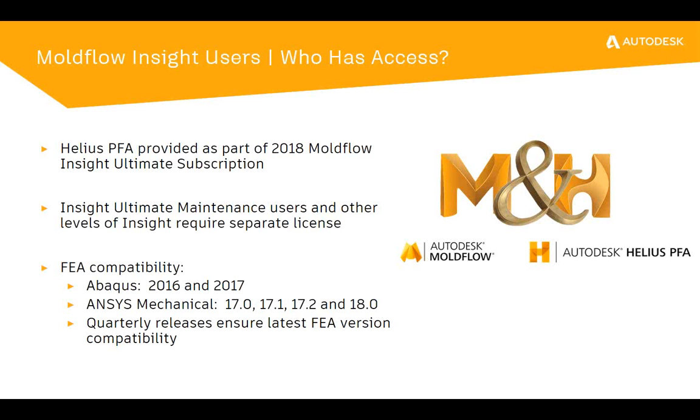Sure, and maybe as an alternative too, if there are two components and you are interested in this information, you could run each individually and evaluate them that way. That wouldn't account for the remelt area, but it would account for each component individually. Yeah, I think that's a great point to bring up, Beth. Account for two different parts, and then you can just treat those as an assembly within your FEA model. But yeah, the remelt region wouldn't have the effects of remelt.